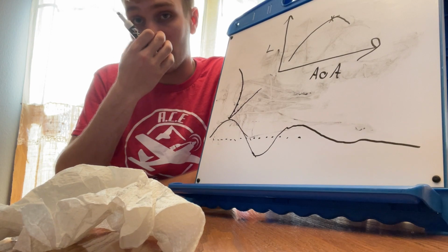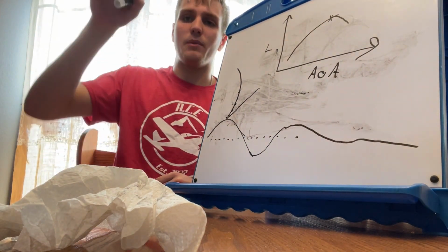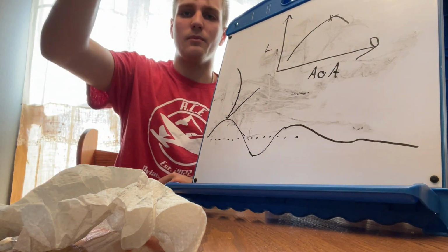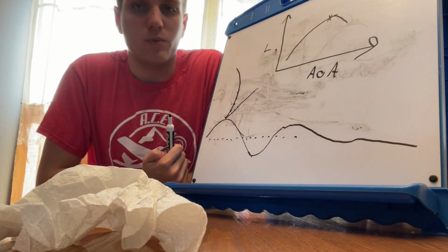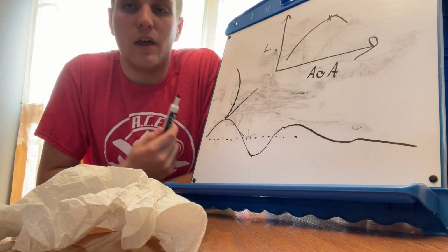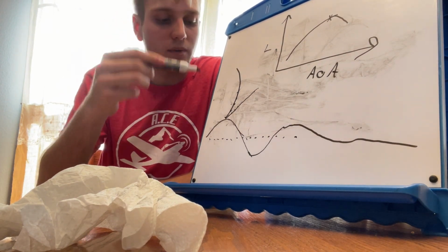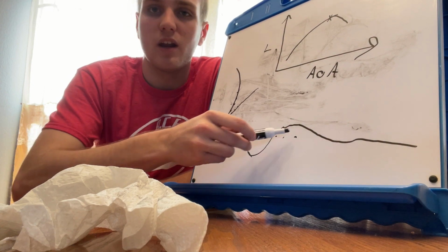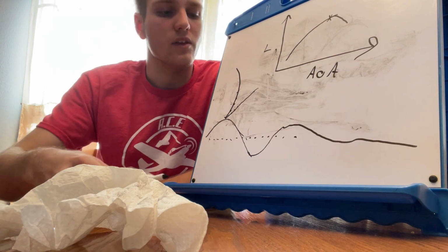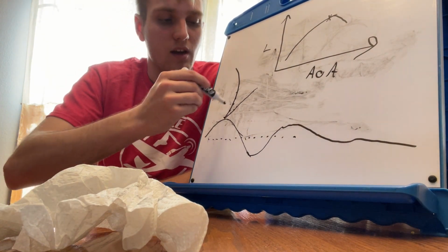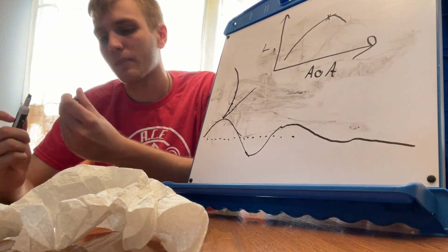If this oscillation gets smaller and comes back to, say, 5,000 feet, we climb up, we go back down, go through our altitude, come back up, come back down. If it starts getting less and less and holding the altitude we did that at, then that would be positive dynamic stability. If you have neutral dynamic stability, it'd be the same thing, but instead of getting narrower, you just have this oscillation all the way down. And with negative dynamic stability, it would get a whole lot bigger over time.